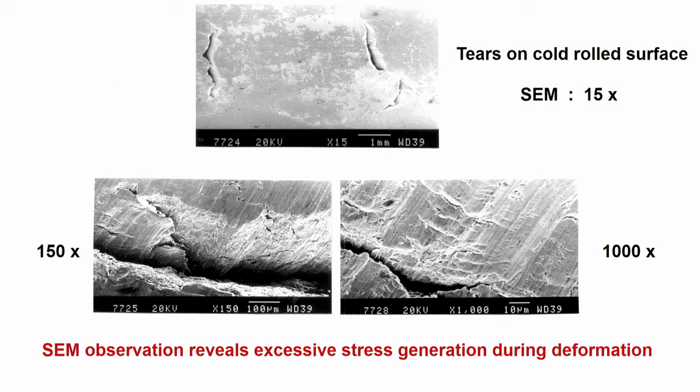To reveal the information you have to go to higher magnification under SEM, because as I have told you, in SEM the depth of focus is more. Even if there are crack formation, it will reveal many things which optical microscope cannot reveal, because optical microscope uses normal light, but the depth of focus is not more. Depth of focus is inversely related to the wavelength of the medium. In optical microscope the medium is normal light, and in electron microscope the medium is electrons.